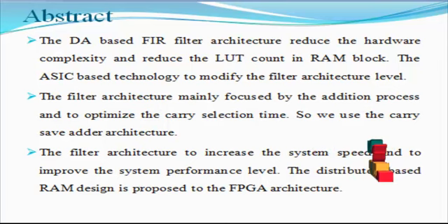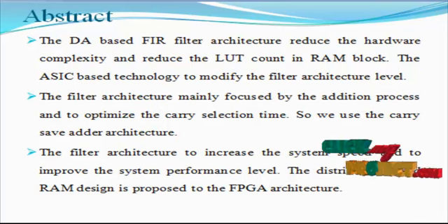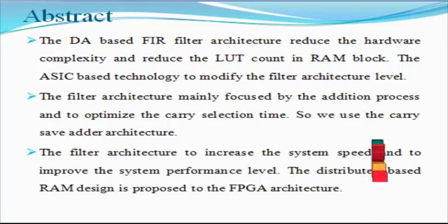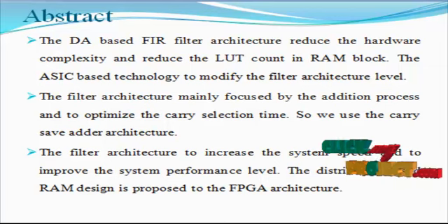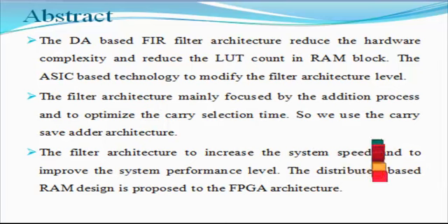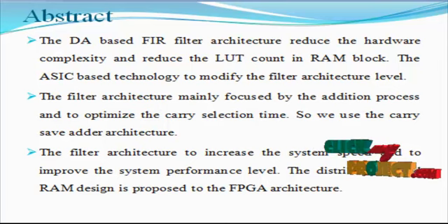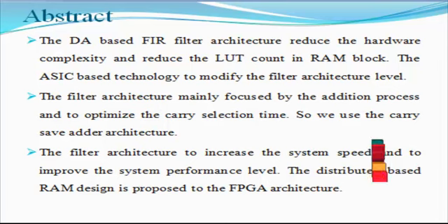Therefore, a shared LUT design is proposed to realize the DA based computation instead of using separate registers to store the possible results of partial inner products for the DA processing of different bit positions. Registers are shared by the DA units of bit slices with different weightage.